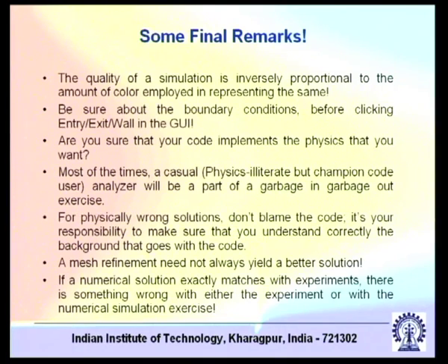If you are unsure about that, first make sure what the governing equations are, and cast those. Is it possible to cast those governing equations in a conservative form? If it is not possible, then this CFD code is not for that particular problem. Everything is not for everything. So it is not that you have a CFD code which you can use for solving any problem.